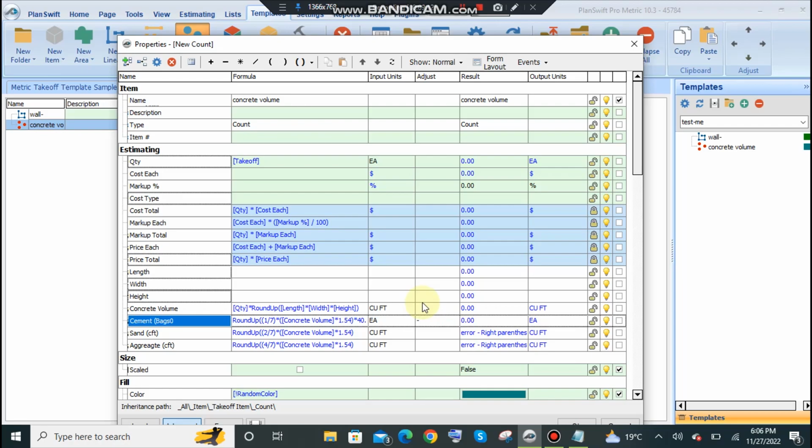After that, what is the height of that column? To get information about height, you need to see the schedule of that column, or you can see the section properties of that column. Suppose this column has a height of 8 feet. So click on 8 feet, click on OK. Now select one by one this type of column, which is only 2 here. Suppose I have selected this. Click on N command to exit that command, or you can press escape from the tab to escape from this type of command.